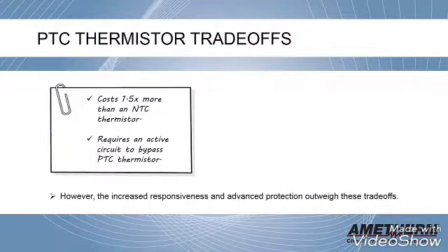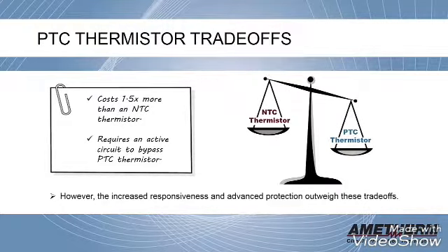PTC thermistors have a few trade-offs. 1. They cost 1.5 times more than an NTC thermistor. 2. They also require an active circuit to bypass the PTC thermistor. However, the increased responsiveness and advanced protection outweigh these trade-offs.